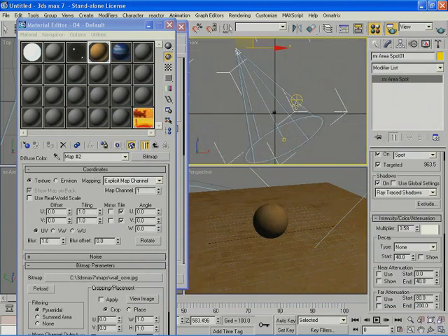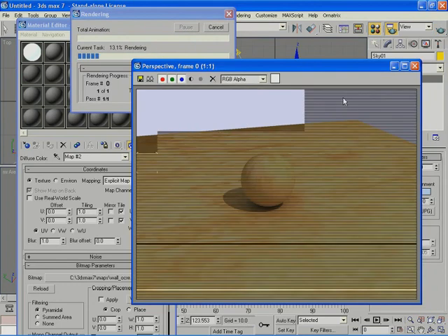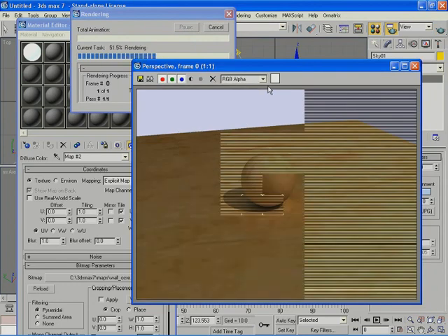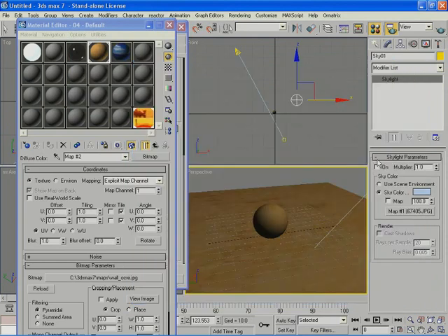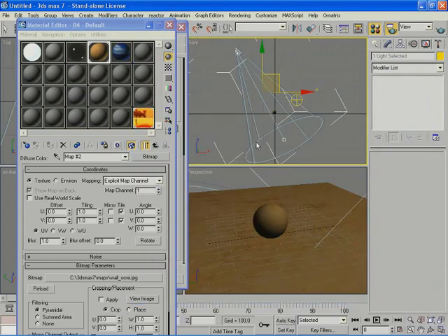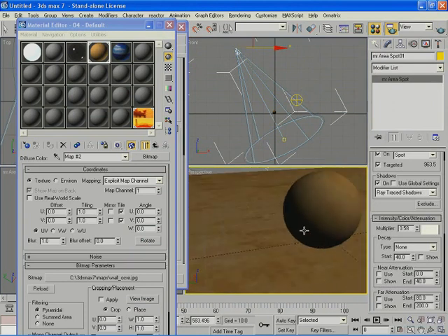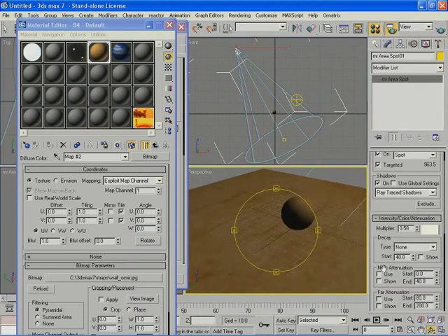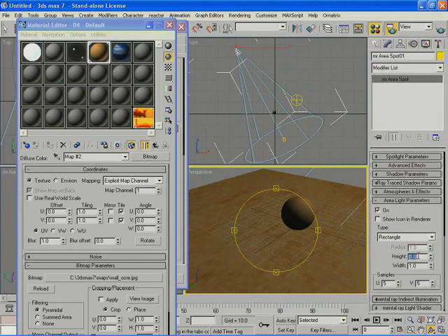Now the last thing I'm going to do is activate area lights. So I'm going to zoom over this area, scroll down, choose area lights on, and increase the height and width. Now here I can only choose disk and rectangle for this type of light because this is a spotlight. In case it was an omni light, I can choose sphere, which would be more appropriate for what we are doing now.